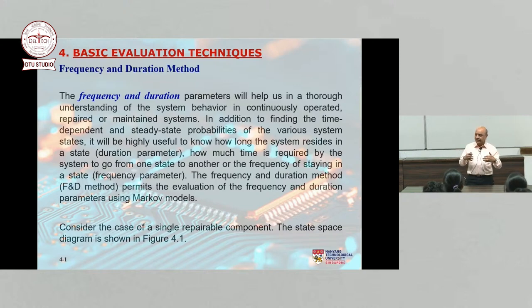So the number of failures is the frequency, how long it will last is the duration. So from our perspective, frequency and duration are more important than anything else, like LOLE, the loss of load expectation, which we shall study tomorrow.